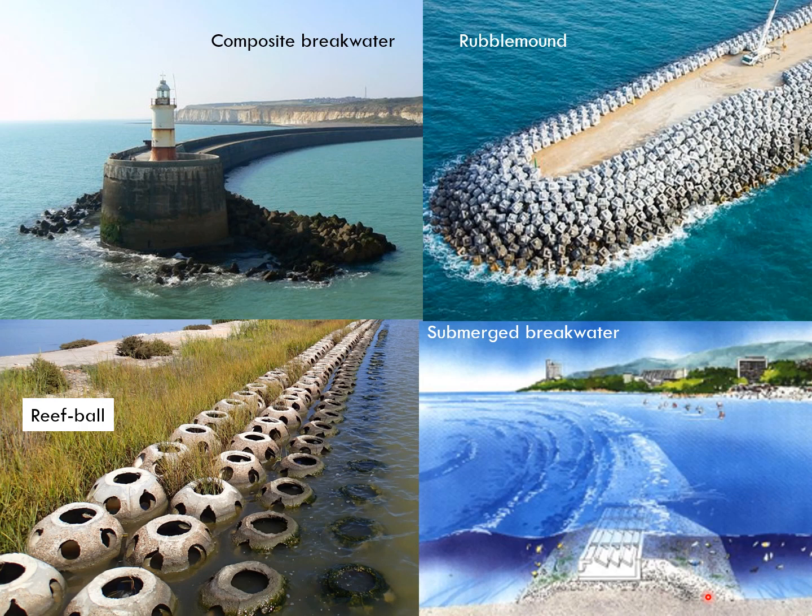However, since the breakwater does not occupy the entire water column, this also means that the wave energy near the water surface can be transmitted to the lee side, and hence the effectiveness of a submerged breakwater is limited. However, a submerged breakwater can still partially reflect wave energy that occupies a large proportion of the water column.